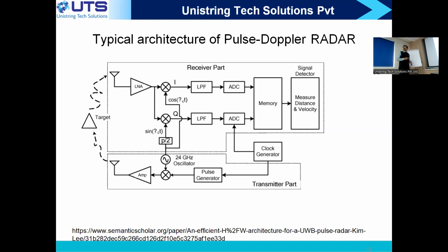We're now discussing a basic architecture of a radar. I took the simplest possible one, so that you can appreciate it and connect with your academic courses. You generate a pulse and you upconvert. You studied superheterodyne receivers in your communication course, up conversion systems, down conversion systems. So you upconvert the signal and you put it into the air through an amplifier and antenna.